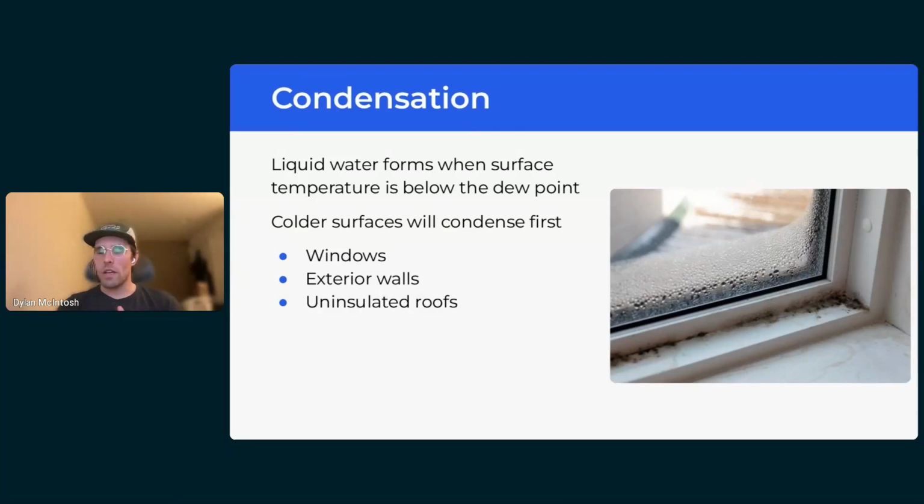What happens in these spaces a lot of the time is you'll have the nails from the shingles in the attic that will cause condensation. So you can see discoloration, dark discoloration around those nails where the liquid water has caused some of the metals in the nails to stain the immediate area, as well as on the floor below. And then the actual sheathing itself. It's very common if you have ductwork that doesn't get completed to the outside, or ductwork that may be leaking from those exhaust fans. I've seen it on exterior walls, specifically exterior walls that are uninsulated, maybe a gap of insulation was missed during construction.